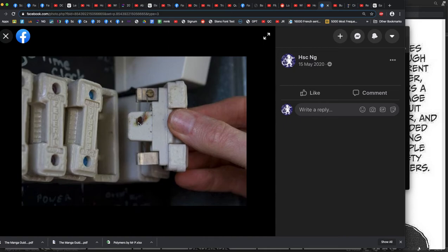There is a thin wire that someone manually winds around this piece of ceramic. And the electricity is conducted through this wire. If there's too much current through the wire, it's thin enough that it melts. And when it melts, you look at all your fuses, figure out which one's melted, and then you take some fuse wire and replace it. Now, that wasn't particularly convenient, and the biggest problem is that sometimes it was quite dangerous. So what people would do, if you were lazy, and I want to specify here, this is really dangerous and you should not do this.